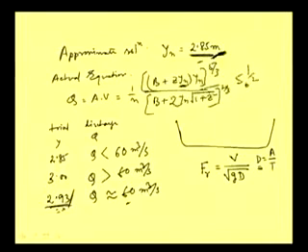So we put that V value and that root over GD value, and the Froude number for that situation we are getting as 0.47. If Froude number is less than 1, this sort of flow is called subcritical flow, when Froude number is greater than 1, it is supercritical, and when Froude number is equal to 1, it is called critical flow. That we did discuss earlier also.